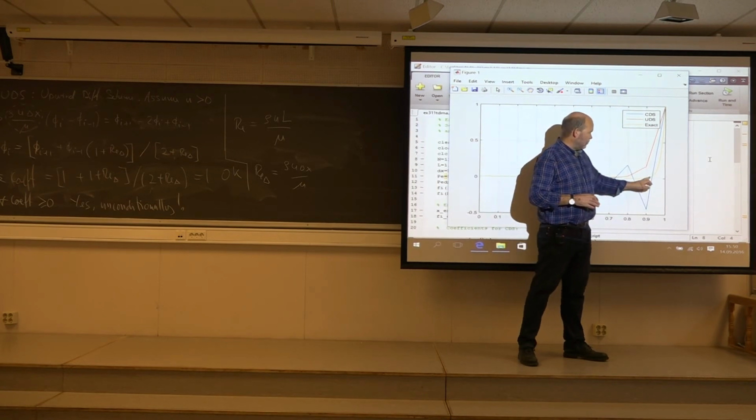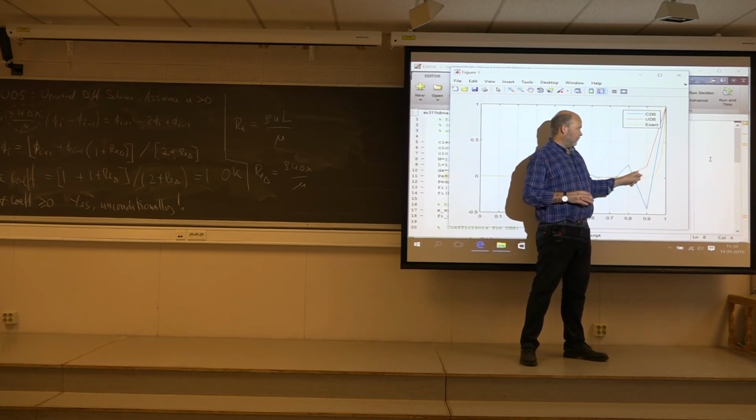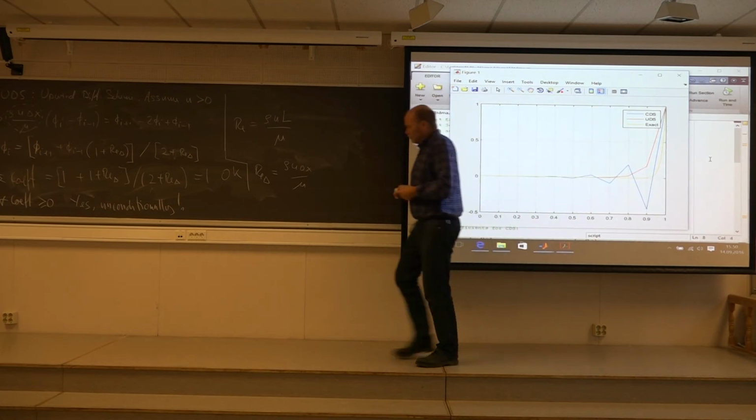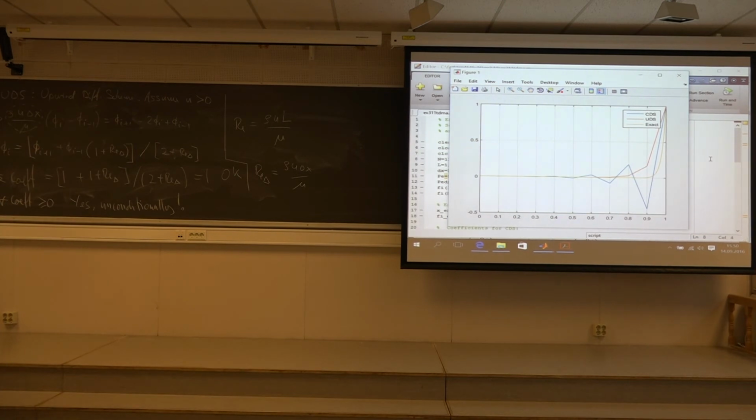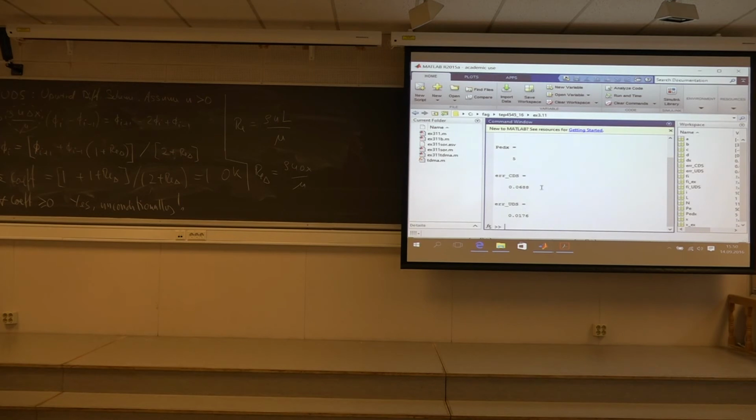The exact solution is fairly much away from this Upwind scheme, but at least you might say the Upwind scheme is stable. Now for the values, the global Reynolds number was still 50, but now the local value is 5. So yes, the central scheme is unstable, and it should be unstable.